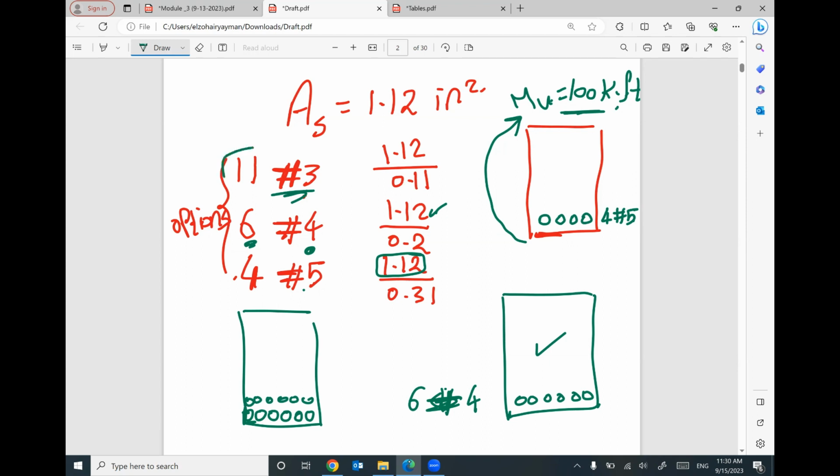But I do prefer the even number here because we will have 2 rows. I don't like this option because more rebars is not good for pouring concrete. This is just for construction, but for design, that's correct. But we have another factor, which is construction, and we are worrying about pouring concrete, nesting and segregation, all of this stuff. We don't like many rebars. So this option is good. You have to tell me one option of these, and it's up to you as a designer.